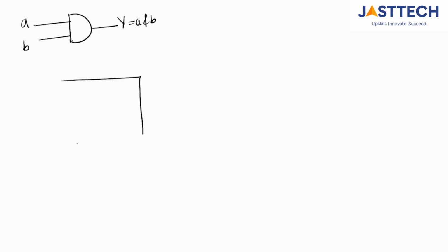So a simple AND gate I am writing. For the AND gate you have two inputs A and B, and the output is A and B. First you need to write the design. This is my AND gate. The inputs are A and B, and the output is Y. Coming from the top module, you are writing it for verification.